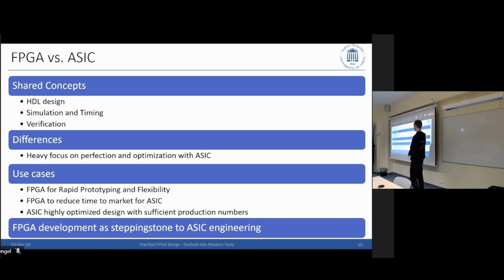The overall workflow, they are overlapping: the limitations, the logic problems, the bus systems, whatever we had, IP cores, all this kind of stuff is very similar between ASIC and FPGAs. So that's something to be aware of. Of course, there's going to be different tooling. But if you use, for example, Catapult from Siemens, then you're using an ASIC FPGA tool. And then you're going to find ModelSim also being used for both of it. So you have a very big overlap between the different domains.